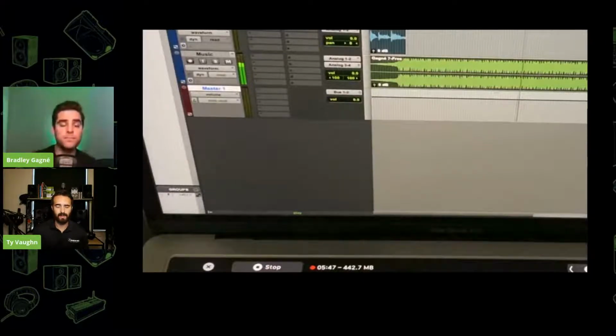That's excellent, Brad. Yeah, and like the ProFX mixer, you do get all those added benefits of having the EQ built in right on the board, the compressor, and all the routing options. But you could also use a standard USB interface, such as our Onyx Producer and Artist series. Essentially, those simple 2x2 interfaces, those little boxes that sit on your desktop, you plug in a microphone, and it goes USB into your computer. But the routing is essentially the same, like you just showed. You just won't have that USB 3-4 playback. You'll just have one playback on those simple interfaces.